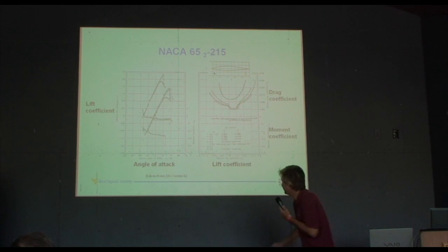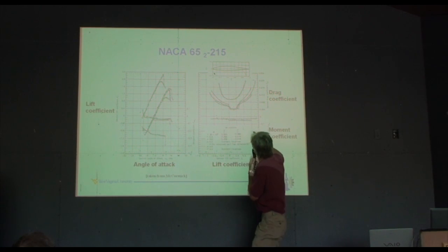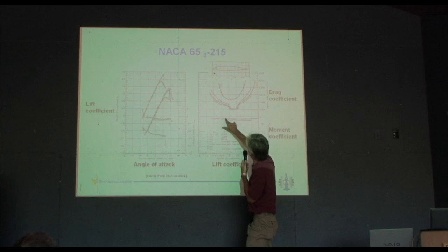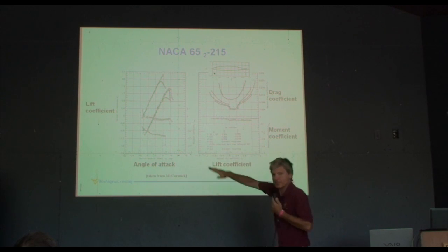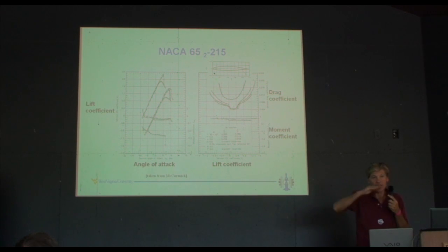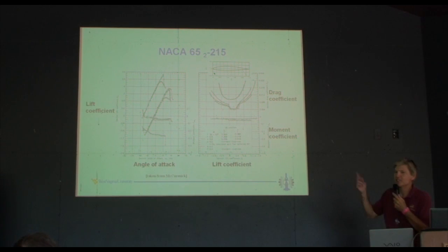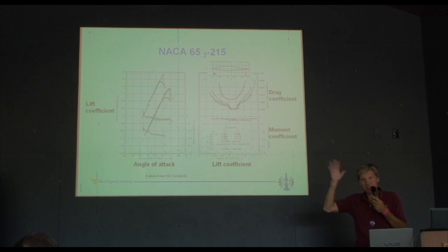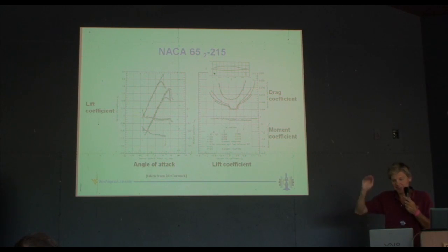And then here, see about 0.025 on the pitching moment, a nice, flat pitching moment line, and it's pretty manageable. That's good for canard designers. If you're looking way ahead, you don't want these really wild, steep pitching moment curves.